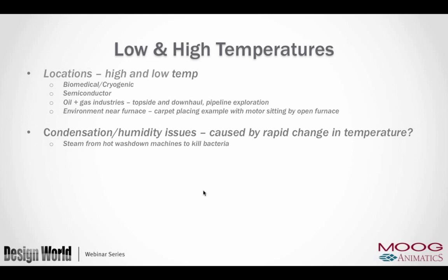Well, let's think about it. A motor can handle 125 C. Yes, it can handle boiling water. The electronics, 85 C sustained. If you wash it down with steam for a moment and it goes away, chances are it never heated up above 85 anyway, and it's not going to hurt it.